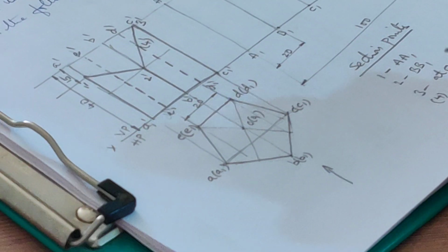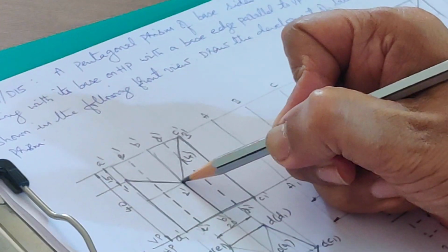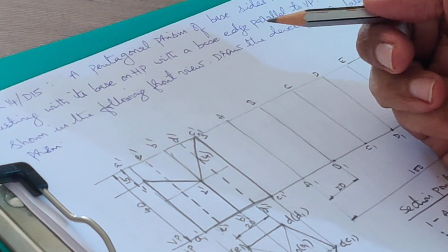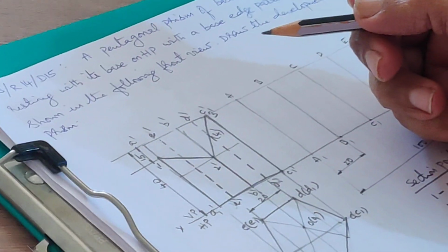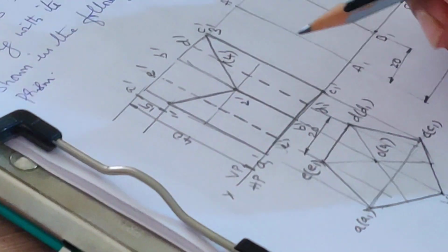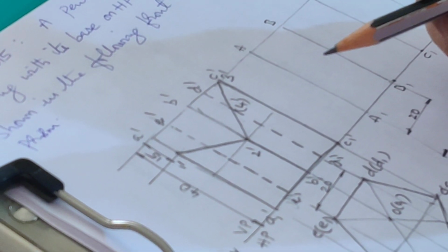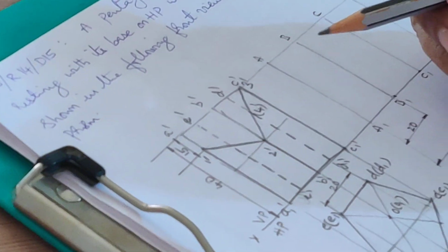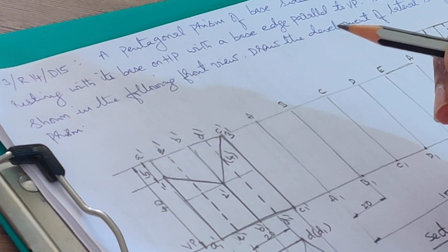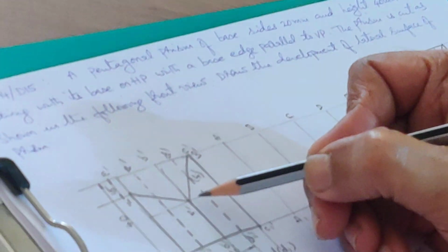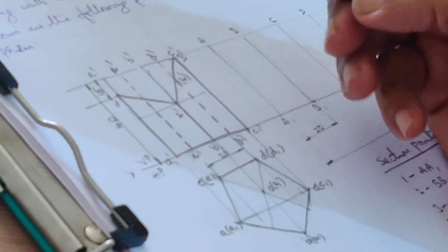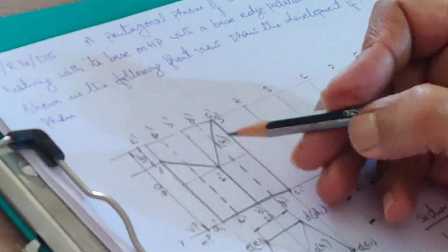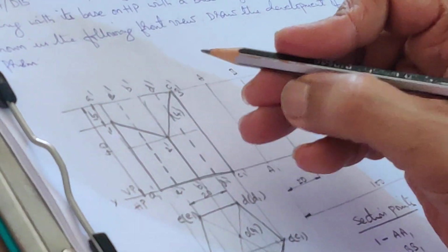Yes, now comes the very important point in this problem, this point. Make it a point whenever the cutting plane changes its direction, that point has to be named by 2 section points. It's very important. Even in the last problem I was mentioning, when the cutting plane cuts either a base or a top face, that particular section point has to be named by 2 section points. Even here, when the cutting plane changes its direction, make it a point, you have to name it by 2 section points. Okay. So if 2 is on BB1, where is the other invisible point?